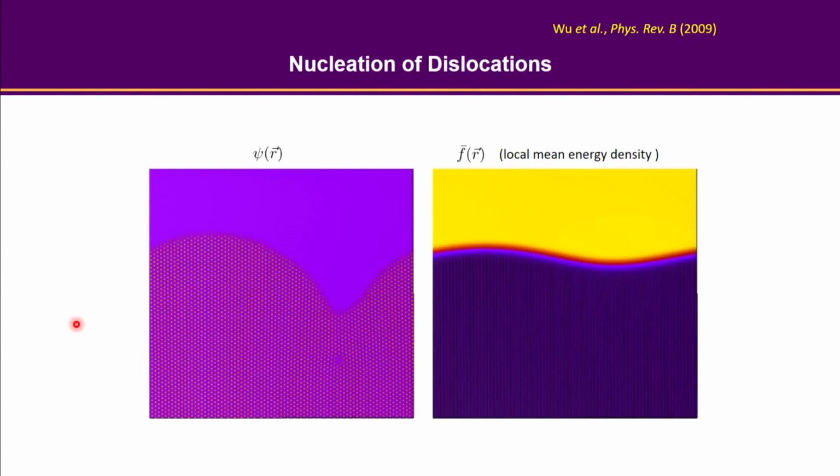So from this stage, you are expecting to see all this plasticity, dislocations forming, coming and going. To a certain extent, if you compress really hard on your material, you are expecting to see a lot of dislocation nuclei, and they are going to react and combine to further reduce the elastic energy of your system.